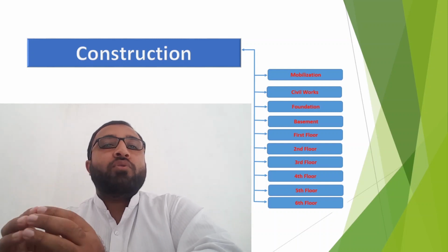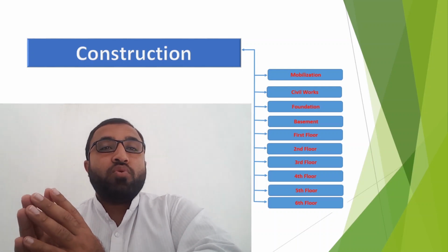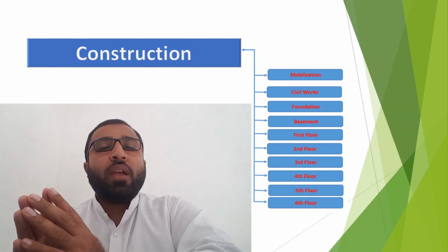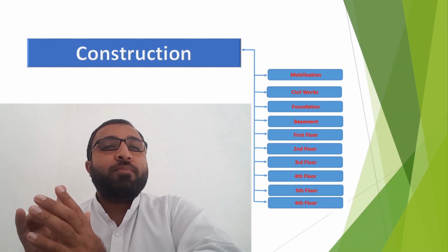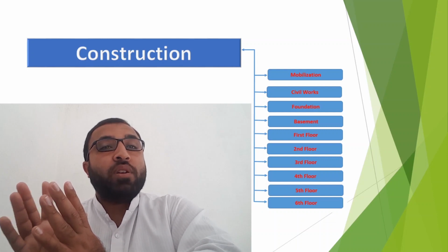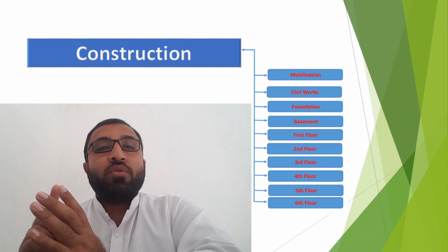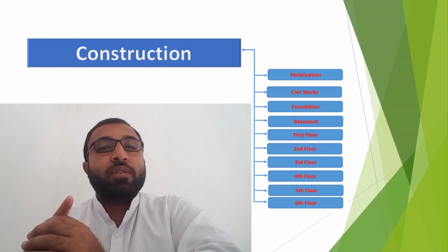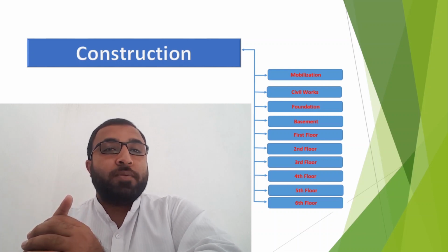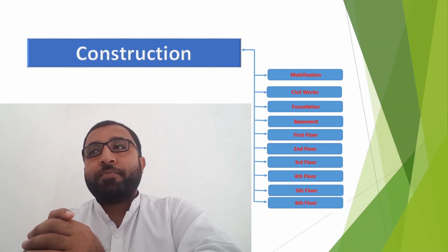First thing, when you have won any contract, the client will give you the NTP, notice to proceed. After getting the NTP, that date will be considered the start date of the project. No matter what the start date written in the contract is, the start date that you will consider in your project will be the NTP, the notice to proceed, and that date we have to mention in our milestones.